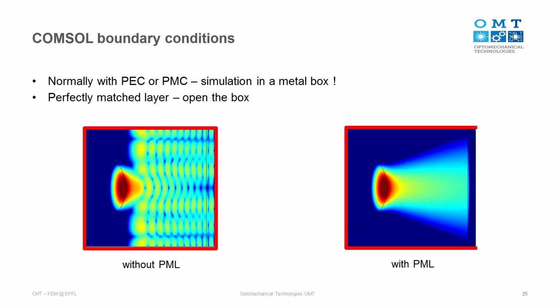Okay. So now we come to the boundary condition of COMSOL. Ideally, I remember there's one question. Normally we just set PEC or PMC conditions in COMSOL. I think that's a picture I copied from Amir 3 years ago, and he has a very nice conclusion saying, normally we're just simulating something within a metal box, which means you have a pretty close boundary, and this is in a log plot, and you will see the interference of the wave when it hits the boundary and gets reflected.